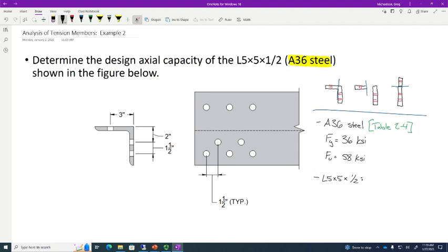So then in a design, if there was a need for a higher strength, then you would use a higher number? Yes, so here's a good example of where that would happen in the real world, okay? So let's say you're the structural engineer on a new building in Denver that's going to be 60 stories tall, right? And you say, well, I'm just going to use 50 grade normal steel, right? And you do the math, and you find these columns are huge, right? The architect comes back and says, those columns are too big. And you as a structural engineer go, well, I'll just use more of them. I'll space them closer together so that each column is responsible for less load. Then the architect comes back and says, well, that ain't going to work either because I need open space.